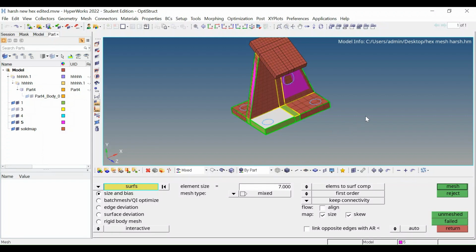So now next we will perform the 3D hex mesh. We will see what a 3D hex mesh is on this surface. 3D hex meshing uses a tool to create a mesh of solid elements. The tool is also called the hex tool. Firstly the 2D meshing is done on the surface, and we have to offset downside, or offset to that element where the 3D hex mesh should be done.